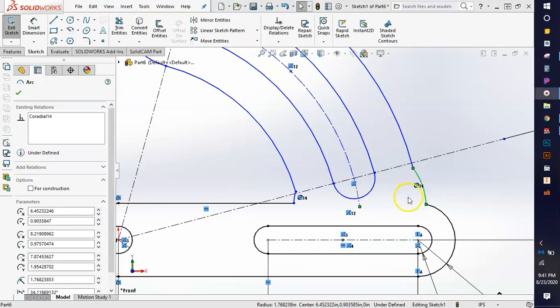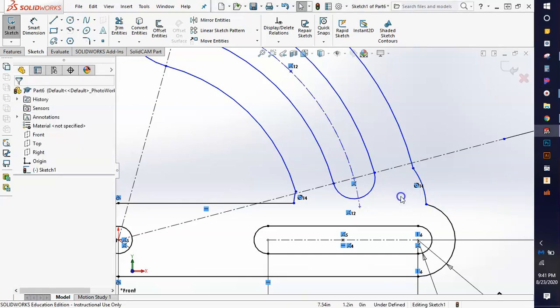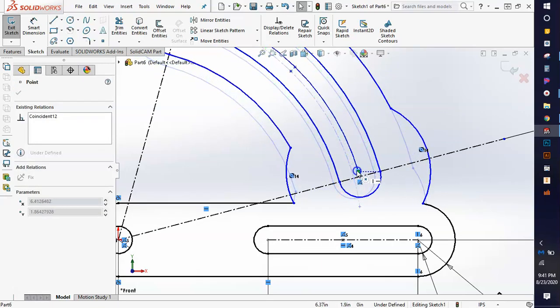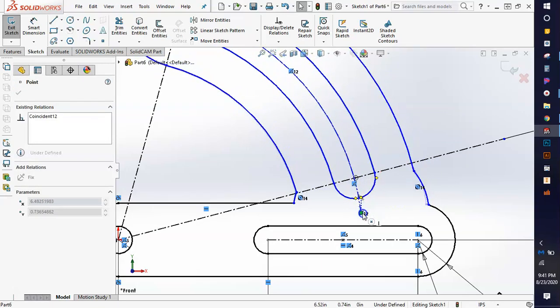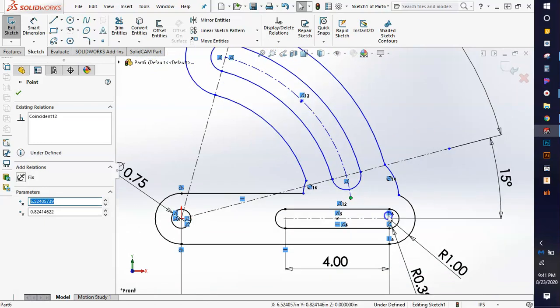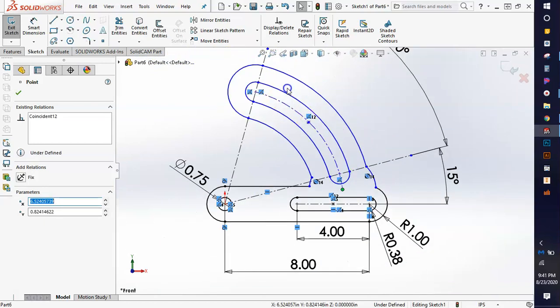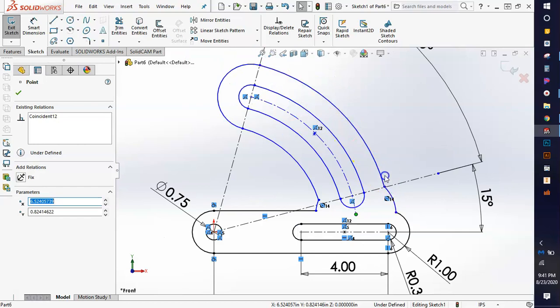Now by moving this around, I can already tell that this is going to cause us problems. You can actually see it took its construction line and everything else, and it really kind of moved this stuff around. So if I was drawing this for myself, I probably would have just used a normal arc tool for this, a normal arc tool for that, and this. But I do want to show you, because I know a lot of students will draw this with the actual arcing slot tool, I do want to show you the problems that you run into.